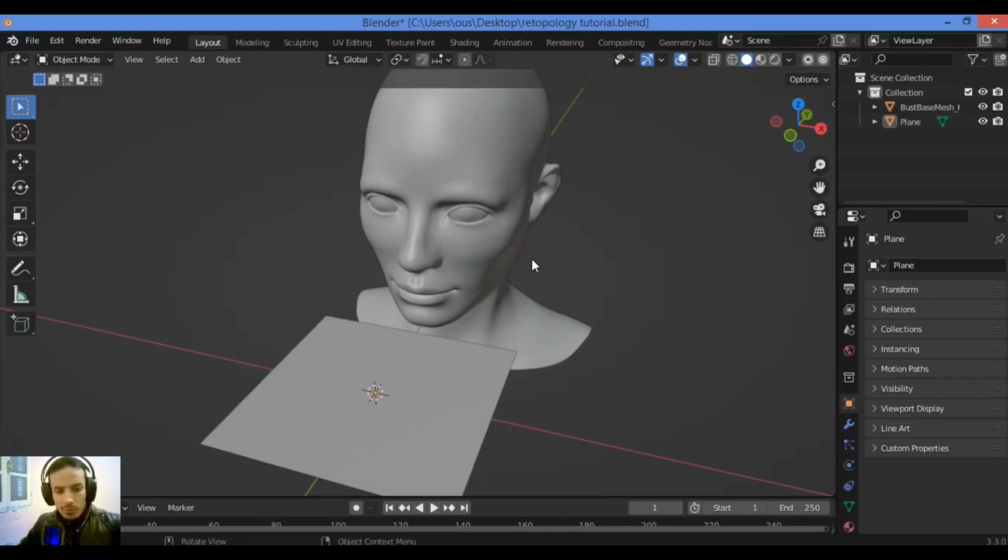The other topology rules will be hard to check if these first three conditions are not met. All of the faces on the model are quads. They each have 4 vertices and 4 edges. There is no duplicate geometry. All of the face normals are oriented in the same direction so that you cannot see the back of the faces.